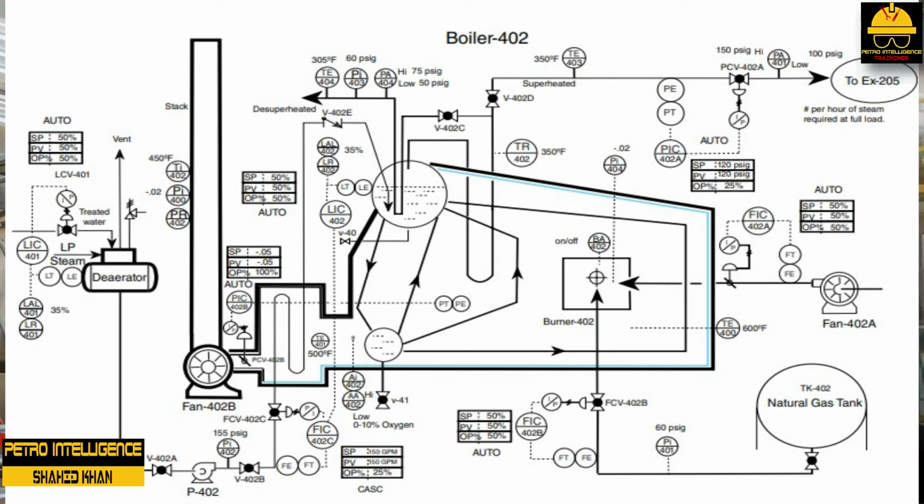Fans provide airflow through the furnace, creating a slight draft or negative pressure. Since the furnace is hotter than the outside air, significant density differences exist. Water temperature increases at programmed rates. Pressure begins to increase inside the large vapor disengaging cavity in the upper drum. As the temperature of the water inside the generating and riser tubes increases, the density of the water decreases and initial circulation is established. Bubbles begin to form and rise in the water, increasing circulation and pressure.